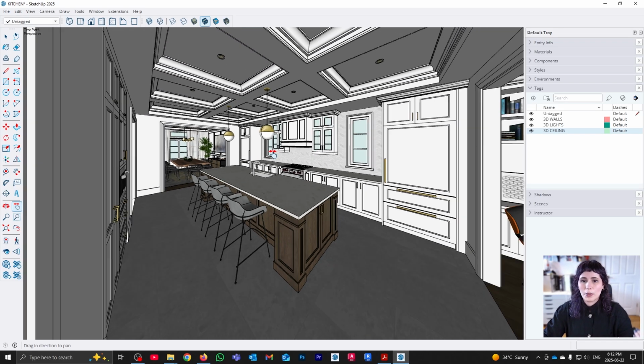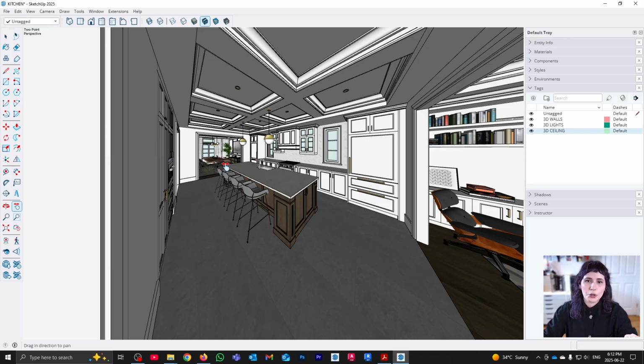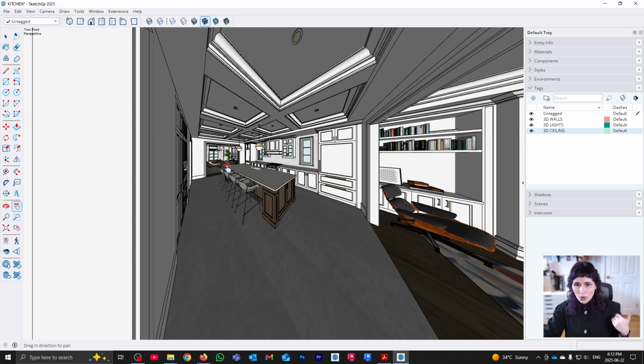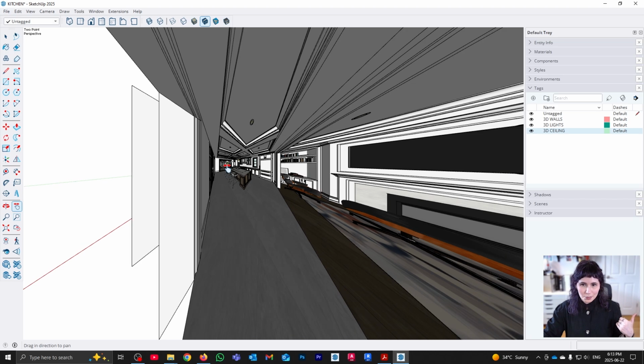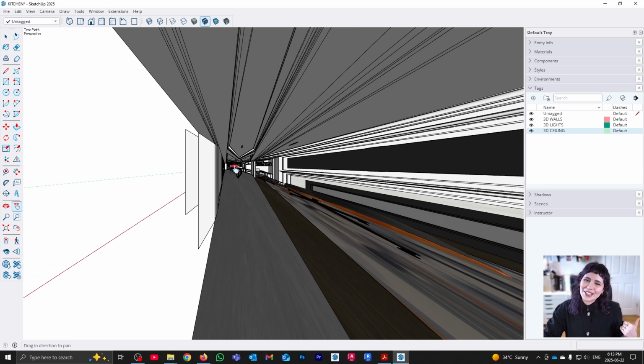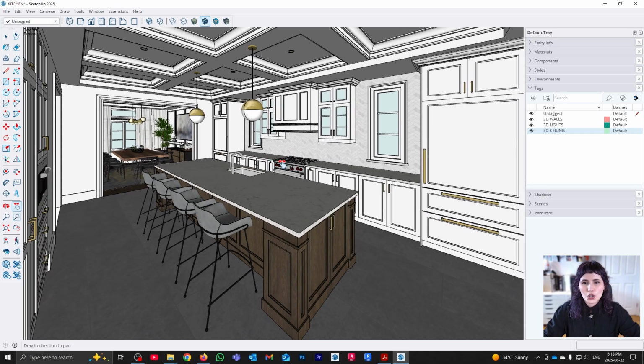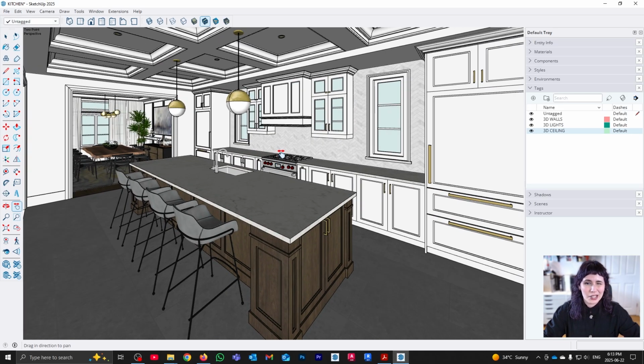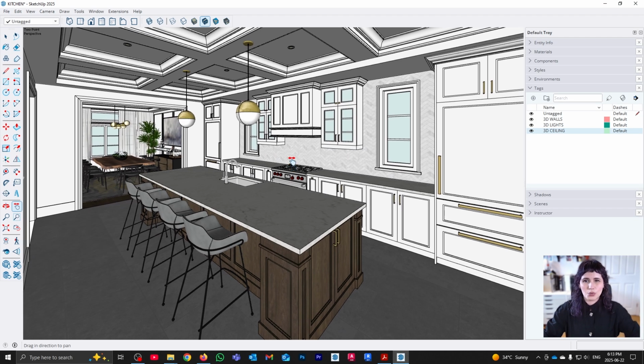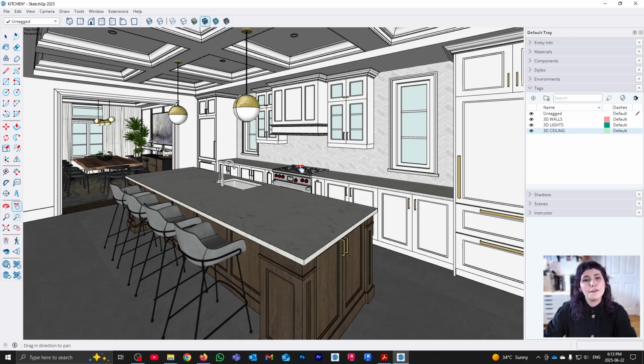I would not recommend that you zoom out too much, because when you are in a two-point perspective, SketchUp will not kick you out of the model, which may sound nice, except that you can really push that zoom out until you generate this black hole experience, which is not very nice. This is all to say that you should try to avoid using the zoom tool once you are engaged with two-point perspective. Basically, you should try to put your camera to see as much as you want to see. So when you switch to the two-point perspective, you don't have to zoom in and out too much. It's more going to be a matter of panning a little bit, choosing basically the focus of your camera.